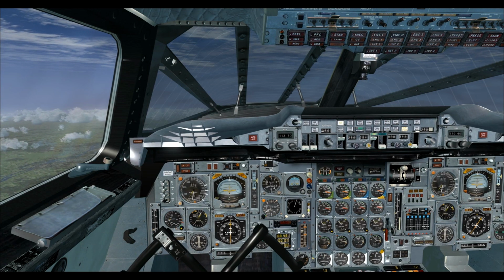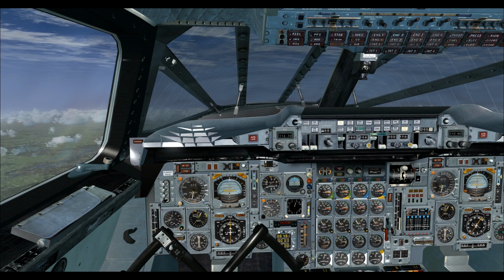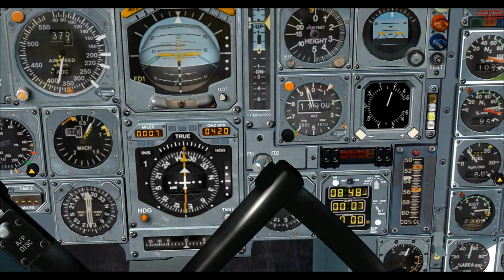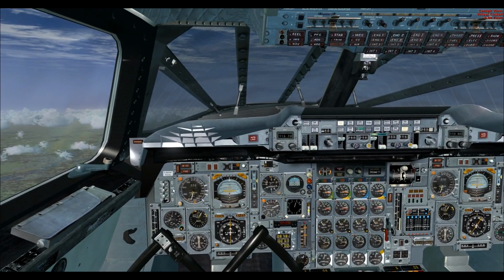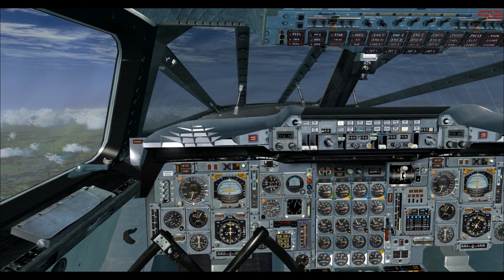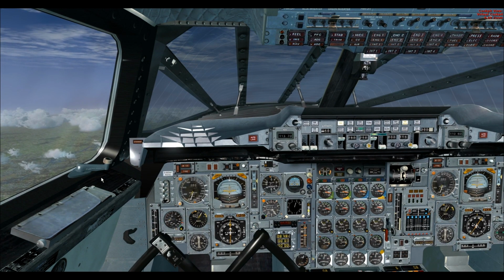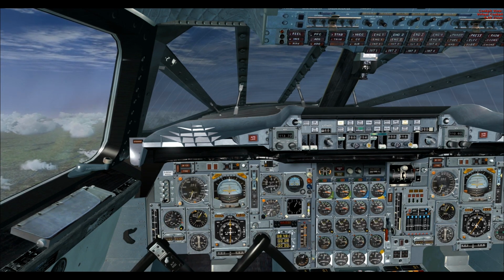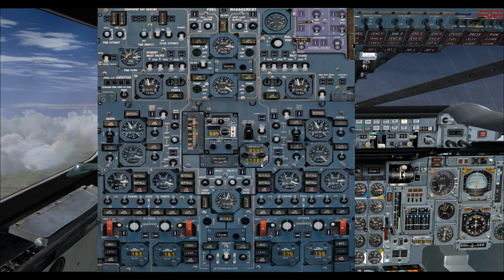We're approaching a speed of 0.7 Mach. I'll just zoom in now to show you that, so you can see that, oops, that's a little rough, sorry. So you'll see we're at 0.7 Mach now, and we're climbing, approaching a speed of 390 knots. I'll just put in my speed now, and I'll come back in a second, but at 0.7 we go through our climb checklist. I'll do the other parts right after this, but I want to get into the fuel part first. So we need to move fuel back at this point.